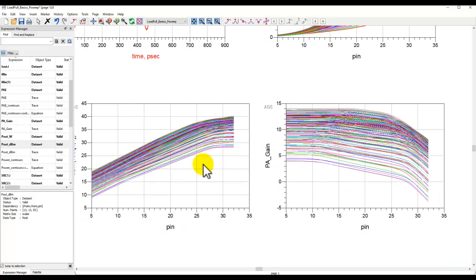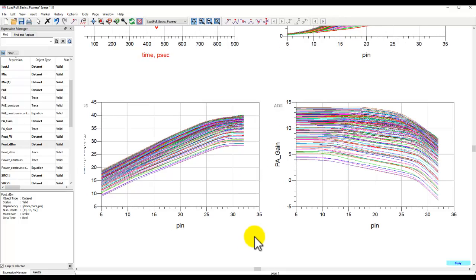So while doing the PA design, when you perform this kind of load pull analysis, a lot of the time you need to do these multiple sweeps to find out what reflection coefficient is giving you the best power and best possible gain, while not compressing your device into a deeper compression level or into saturation. Now also you notice different load reflection points have different compression levels. For example, if you look at this trace, by the time you reach maximum power, you're already deep into compression.